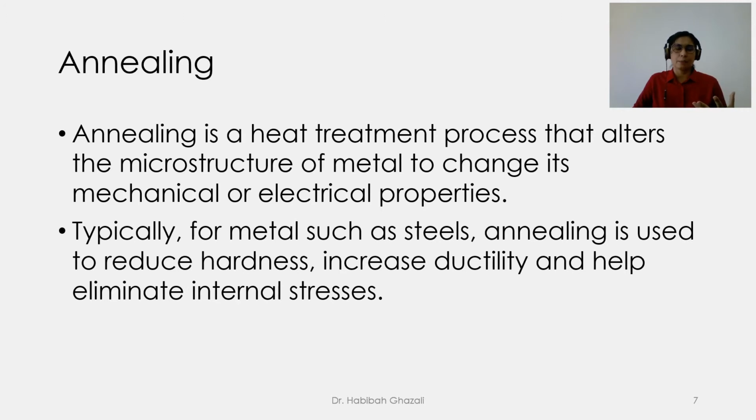So this metal, typically such as steel, when we perform the annealing process heat treatment, it will reduce the hardness of the metal, and in return we will get the metal with high ductility so that we can process it even further. And also, the annealing process will help eliminate internal stresses. Internal stresses can be generated by the strain hardening effect as well.